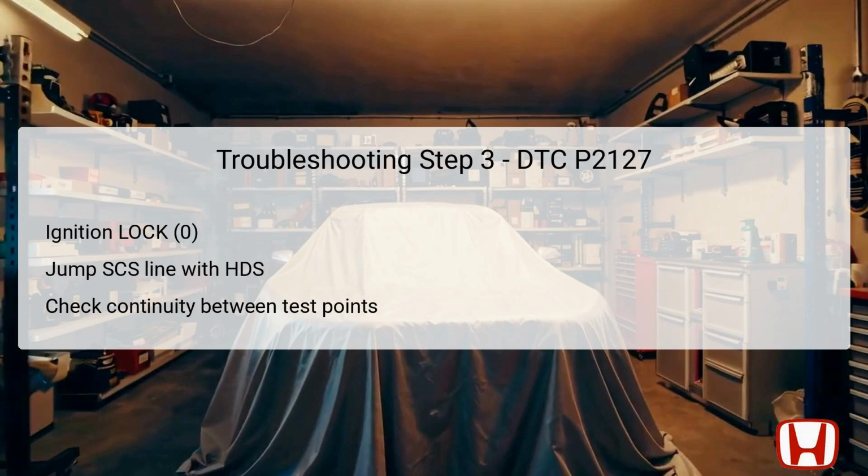During Step 3, set the ignition to LOCK 0 and use the HDS to jump the SCS line to prepare for the next test. Disconnect the ECM connector A, specifically the 49P type. With both the APP sensor 6P connector and the ECM connector A disconnected, you will check for continuity between the defined test points. The focus here is on the APS2 wiring, testing from the APP sensor 6P connector number 1 pin to a body ground.